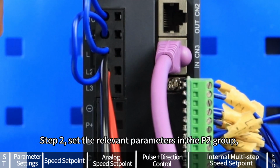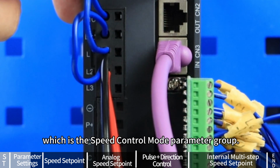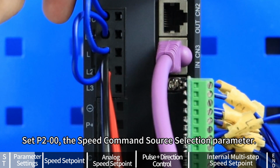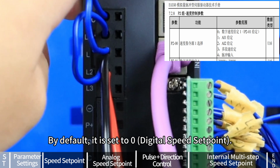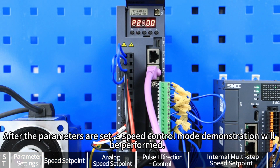Step 2, set the relevant parameters in the P2 group, which is the speed control mode parameter group. Set P200, the speed command source selection parameter. It can be set from 0 to 4. See the table in the upper right corner for details. By default, it is set to 0, digital speed set point. After the parameters are set, a speed control mode demonstration will be performed.